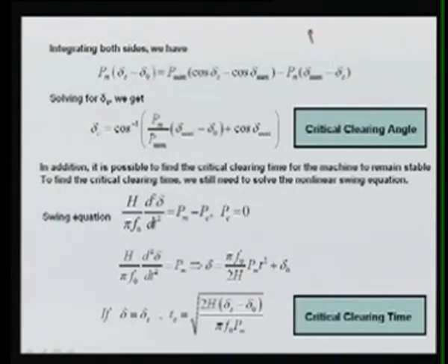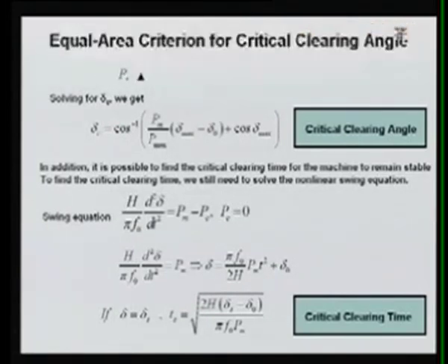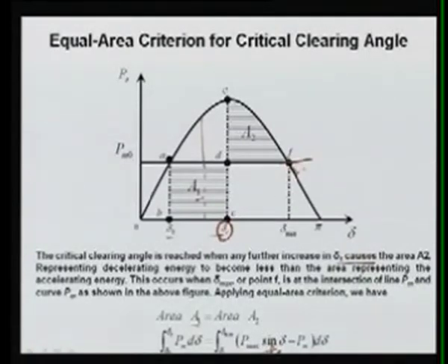Here we know this Pm is your Pmax sin delta max. So if you will solve this, knowing this Pm as well as Pmax, you will get the two values of delta max. Means here in the previous case, if you will write this equation, this Pm will be equal to, this is the Pm at this F point, it is your Pmax sin delta.